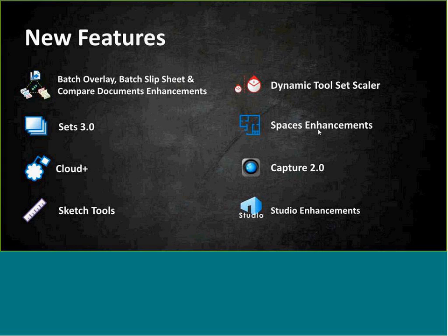Also enhanced, Spaces. At its core, Spaces allows you to sort and report on markups based on the user-defined zone they reside in. Well, with Revu 2015, you can now copy and paste spaces across other pages and files, create an area measurement directly from the space, and you can add hyperlinks to and from spaces placed in the document.